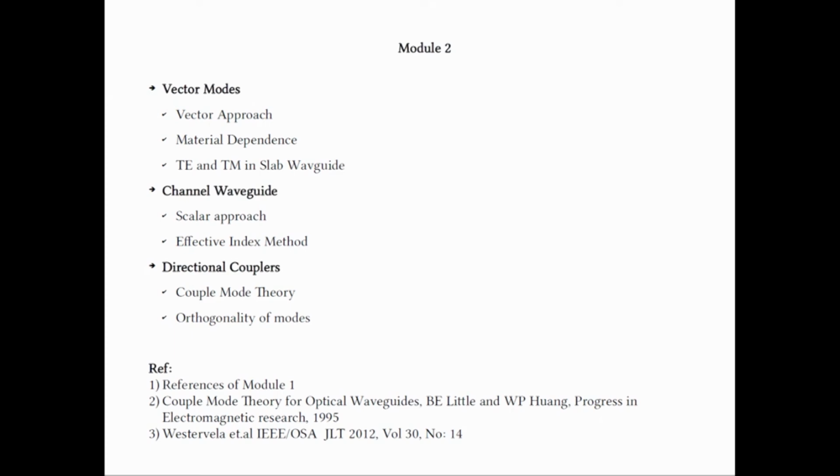After substituting the superposition into the scalar wave equation, we obtained a set of differential equations for A and B, which are called the coupling equations. The coefficients of the coupling equations are Kij, which consist of all the parameters of the structure, like the spacing between the waveguides, the waveguide design, the refractive index contrast, the operating wavelength and so on and so forth. In particular the spacing is a very sensitive element. As you increase the spacing, the coupling reduces and more length is needed to couple the waveguides.